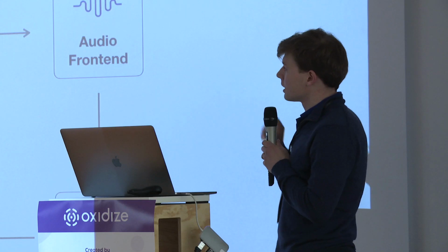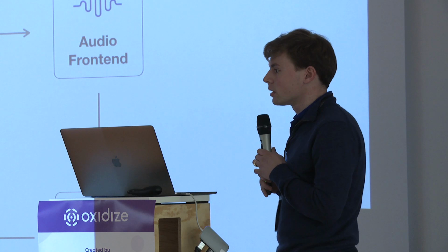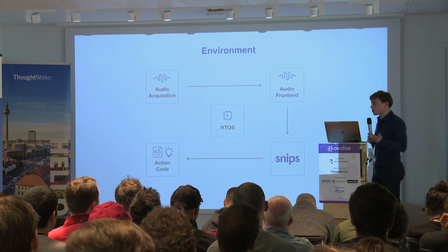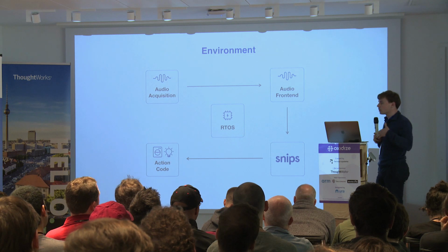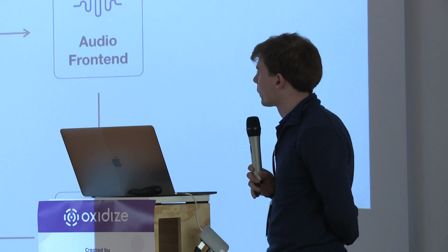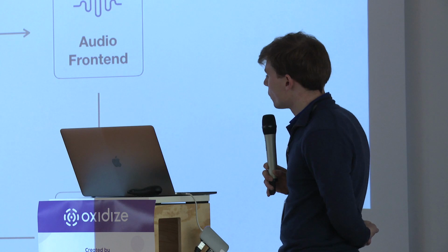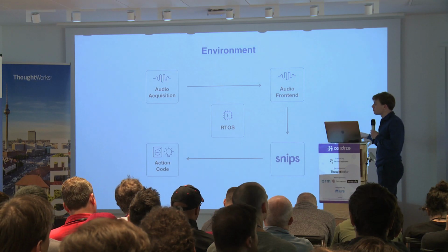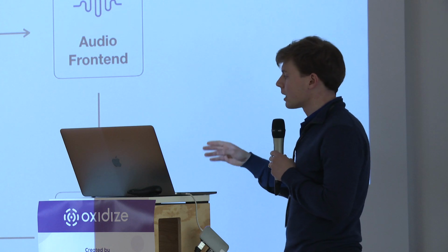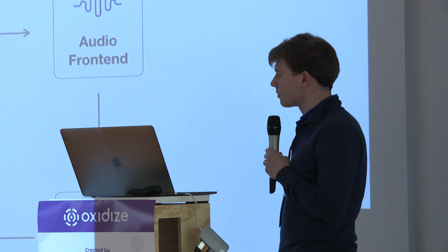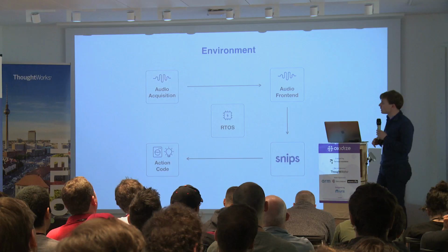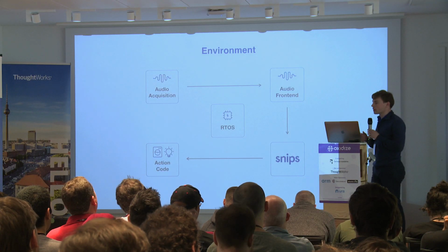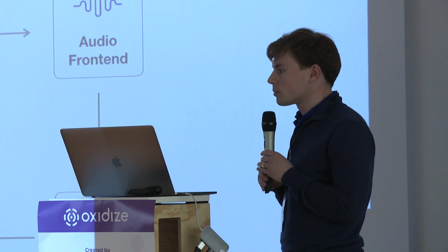The first two bricks are not developed by us, so we don't know exactly how much processing time and RAM they will take. We need to be comparable to them. Then we have Snips, which takes the audio source and maps it to an action that the end client will execute on the device. Everything will usually use a real-time operating system because it starts to be quite a complex system inside the MCU.